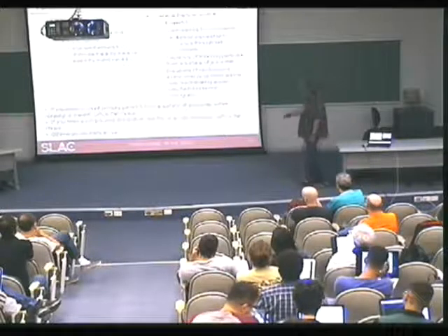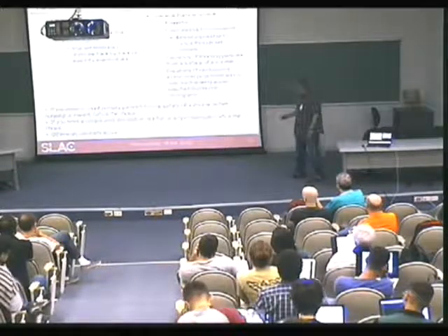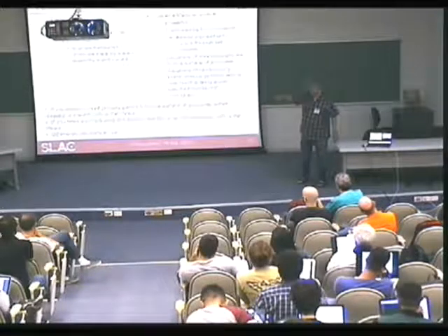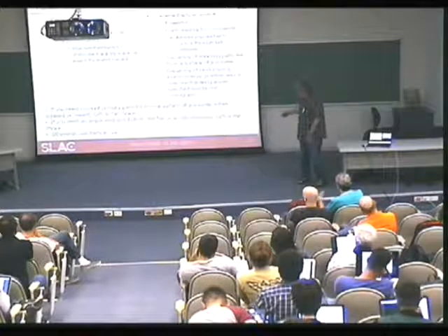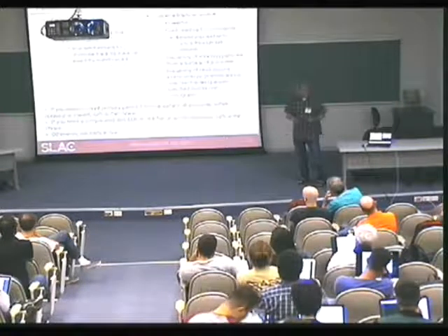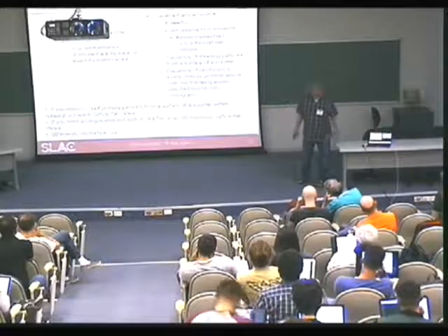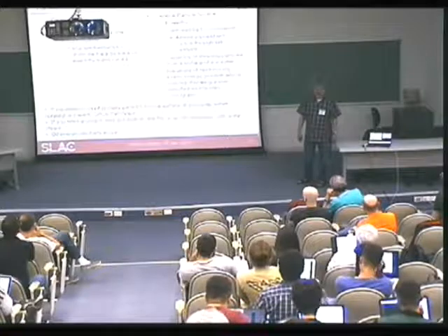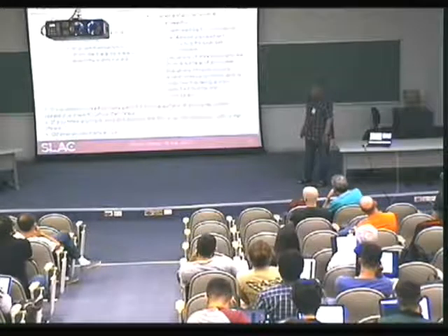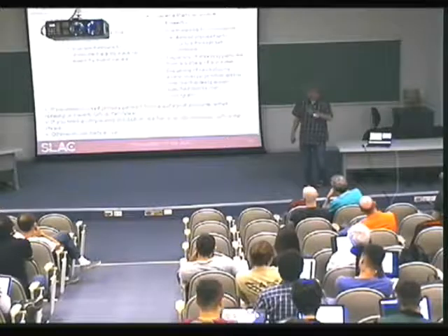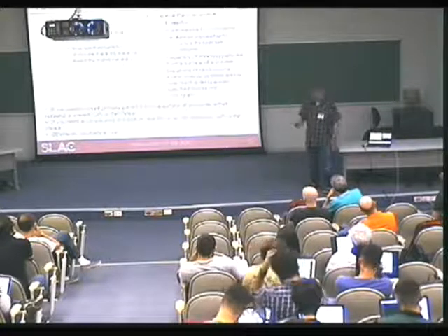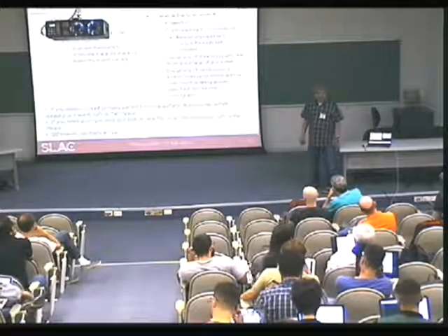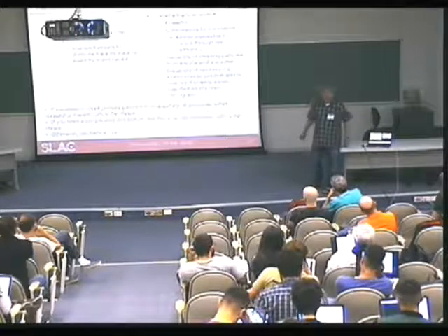If you need a very complicated distribution of the momentum, for example not Gaussian but whatever shape, GPS is the solution because you can always provide histograms. Otherwise, please use the particle gun, so you really understand what you are doing. Far more than half of the questions on shooting primaries always come for the general particle source. It's complicated. Big warning here.